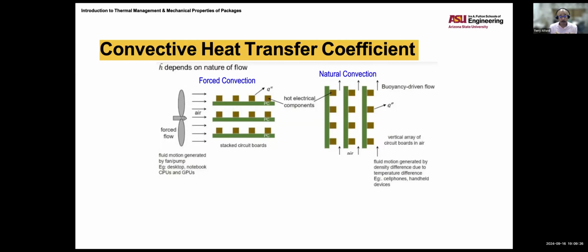That's when I talked about the turbo boost power and temperature management technology that Intel uses. When the CPU is overheating or in a range where it's going to overheat, the fans come on really hard. They stay on for 30 seconds to 2 minutes, but they're full tilt trying to bring the CPU back down. Again, that's forced convection.